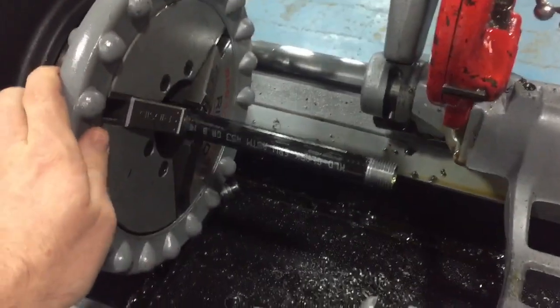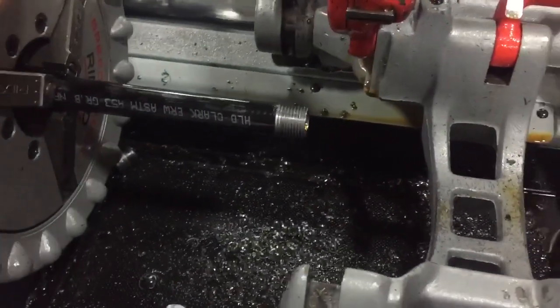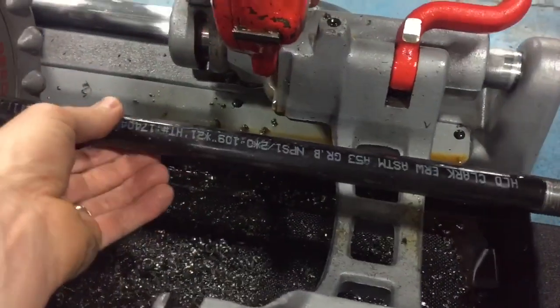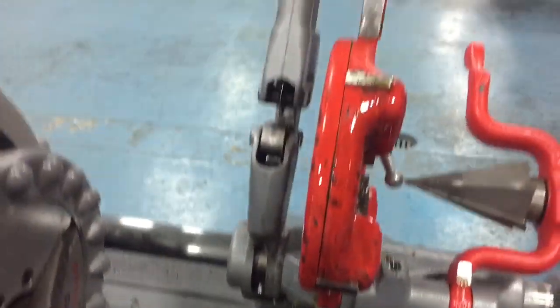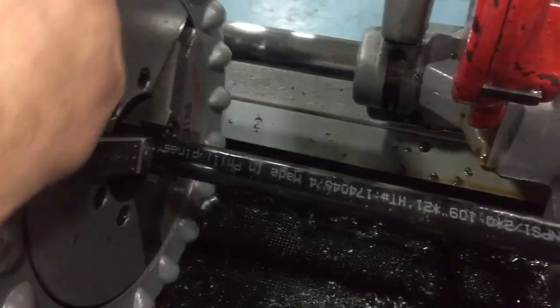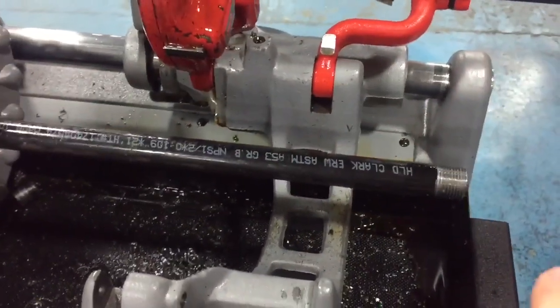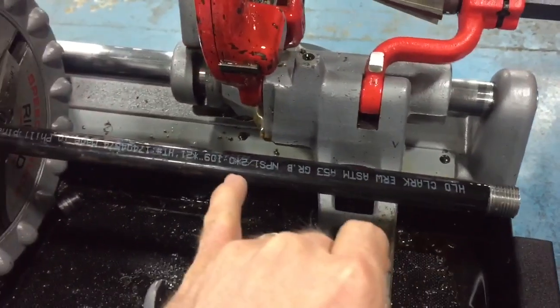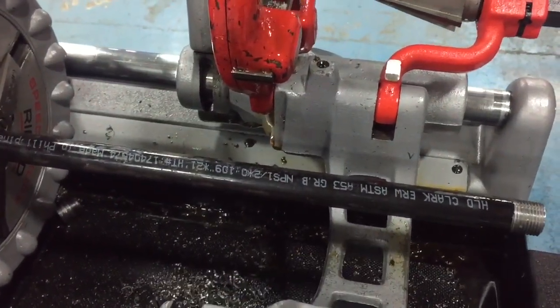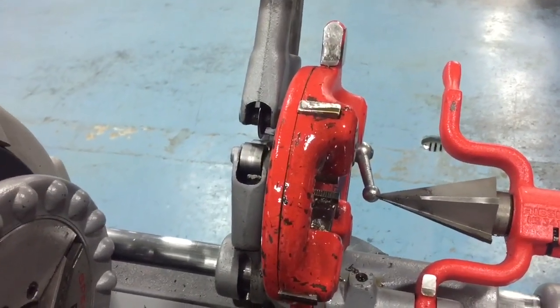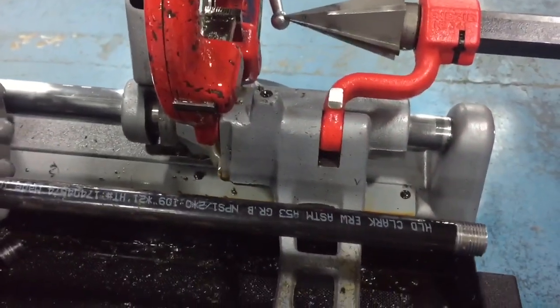Right, so the first thing I'm going to need to do is loosen off the chuck here, so I just back it off and then slide the piping out. So we have enough, and just keep in mind we can move the cutter back and forth with this hand wheel down here, and then we will tighten this back into place. And what we're going to do is use the tape measure and measure from the end here to the cutter over here, to the wheel on the cutter, and make sure that it's at 6 3/4 of an inch.